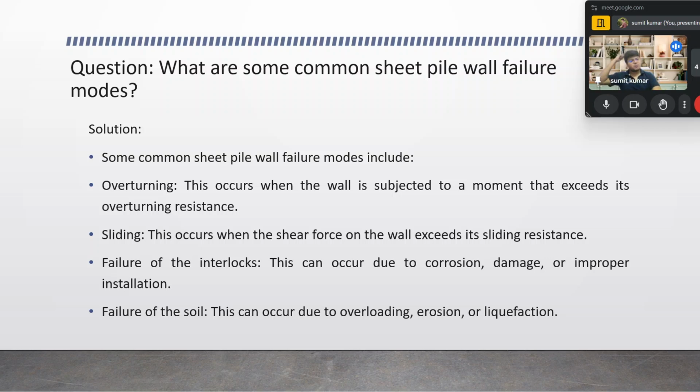When you provide some acceleration through the ground surface during the vibration, we install an acceleration measuring device on the topmost section of the structure we have stood on that sand surface, and we find how much the ground acceleration is enhanced when it travels up to the surface level. Those things you can go across and see, and understand up to an extent. You can also find some YouTube tutorials.